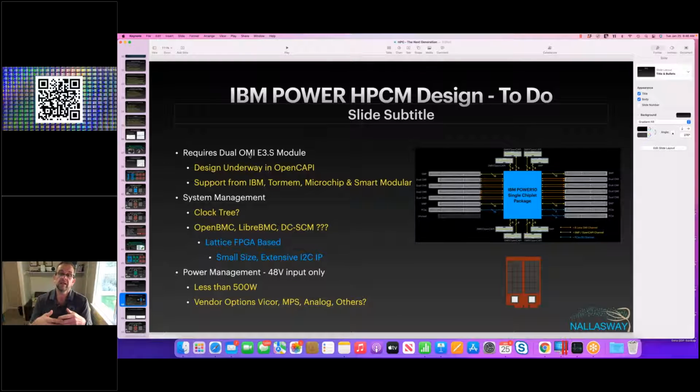OMI is focused purely on the low latency memory channel. The Open Memory Interface is a serialization of the low latency DDR bus. And so it's very complementary to CXL. So what I'm trying to do is say, you can plug in CXL modules if your processor wants CXL, you can plug in OMI modules if your processor wants OMI.